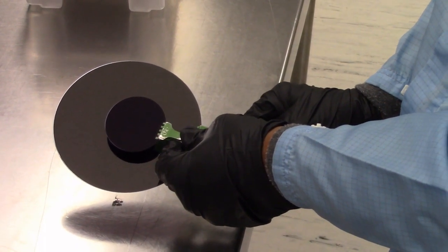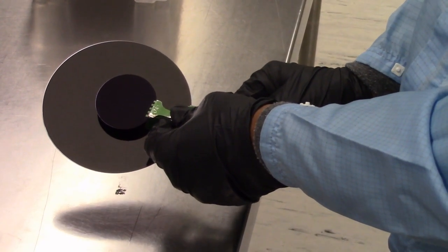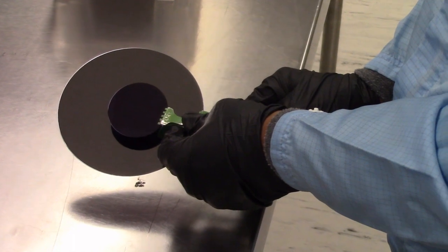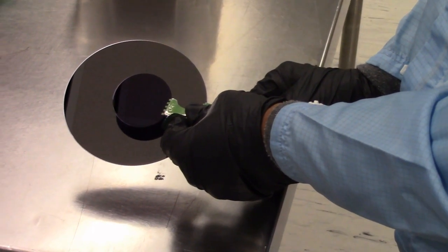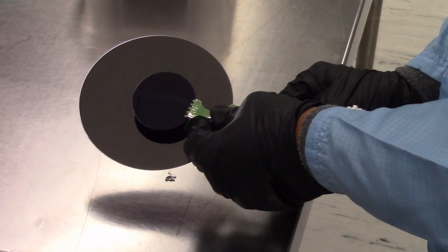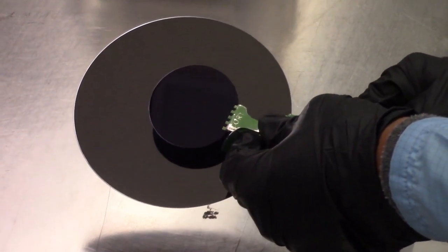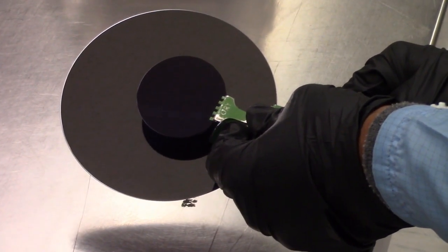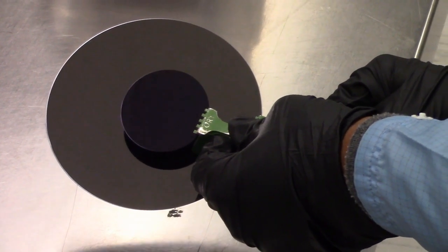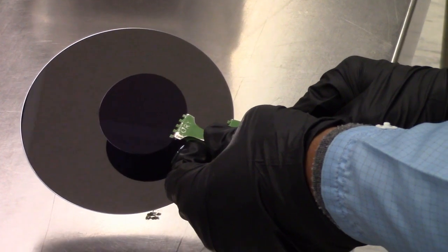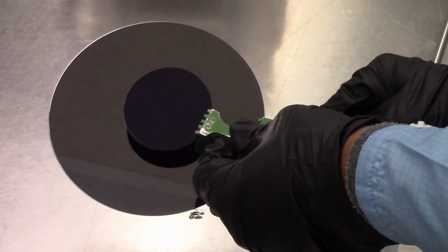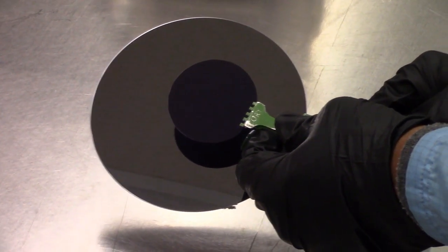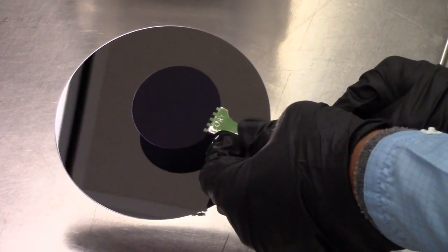Okay, now that we have taken the wafer out of the furnace, it's a good thing to do a quick sanity check to see if we have actually grown an oxide. The way to quickly check this is to see the color of the wafer. As you can see, different thicknesses of the oxide show slightly different colors under white light. For oxide that is around 100 nanometers, you would expect to see a royal bluish to violet color, which you see for the wafer that was put into the furnace. The wafer shown in the background is a silicon wafer, which is silicon-ish in color without any specific color, as a reference.